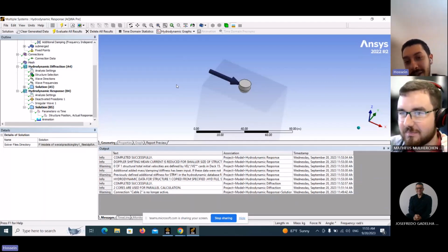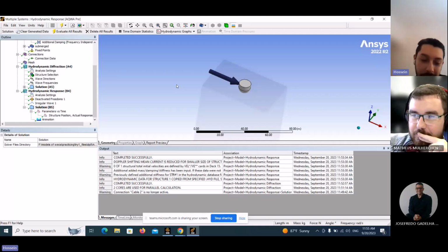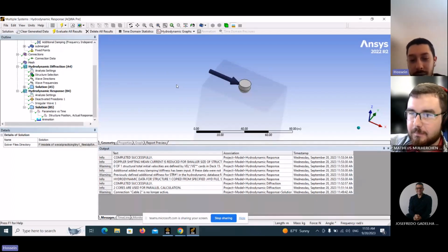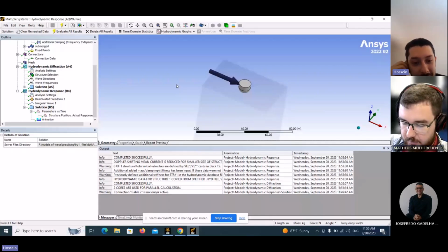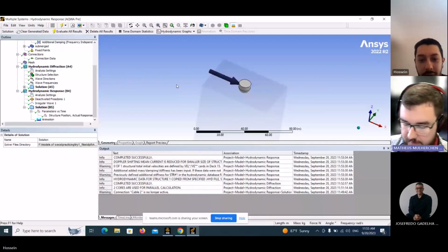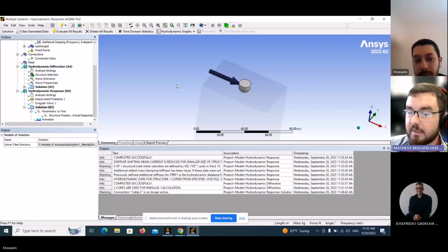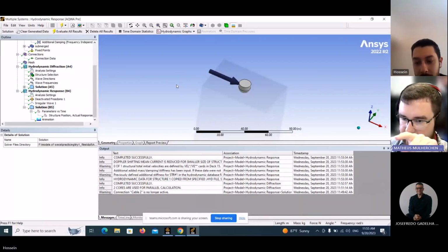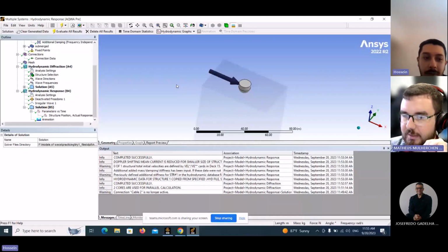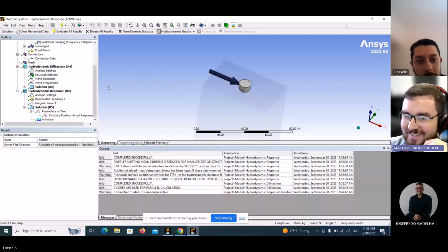How do you define the thickness of your structure? What is the number that you assumed? You have the density of the water and the volume that is immersed. From that you get the mass that the structure needs to have. If you go to the structural tool box and play a little bit with the thickness, you can keep changing it until the value comes to the value that you calculated. That's how I did it, like a trial thing. But it's not very nice. It's not automatic.